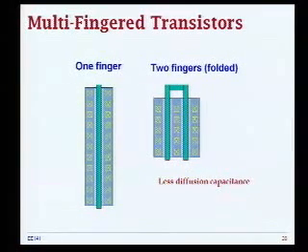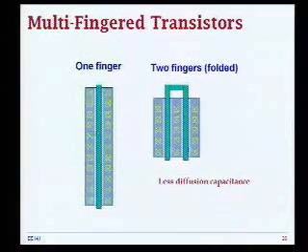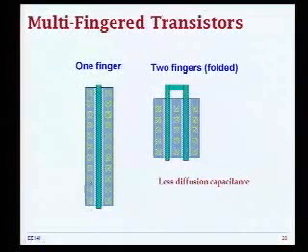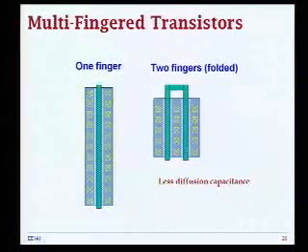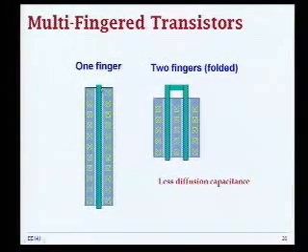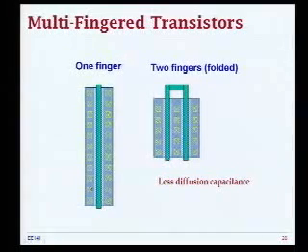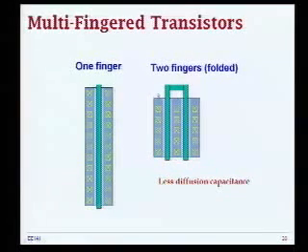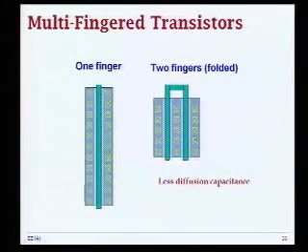Okay, so this is a strategy now to cope with extremely wide transistors. You can have a real requirement for a really wide transistor, and in this case, if you just use really wide diffusion, then you will have, first of all, a lot of contacts that creates a lot of diffusion capacitance. But a better approach and oftentimes used is to have these multi-fingered configurations.